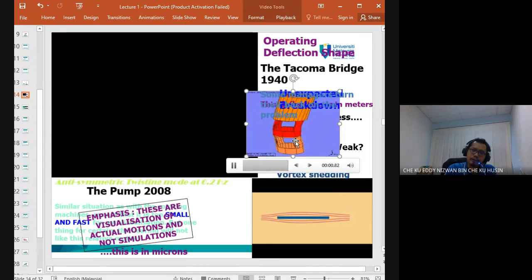After measuring the natural frequency, we found that the motion coincides with one of its natural frequencies, so there is a resonance. This is the way we analyze the vibration issue, because this is very high vibration, exceeding the maximum allowable range.